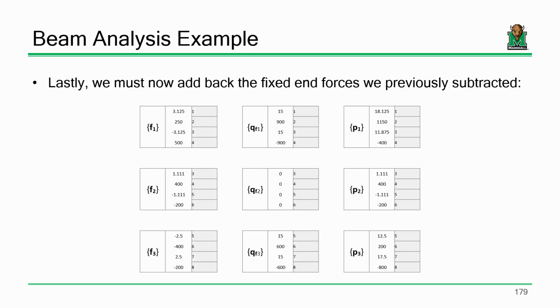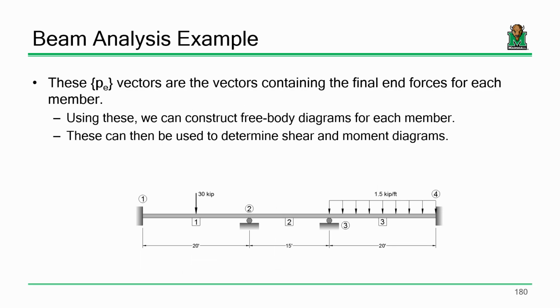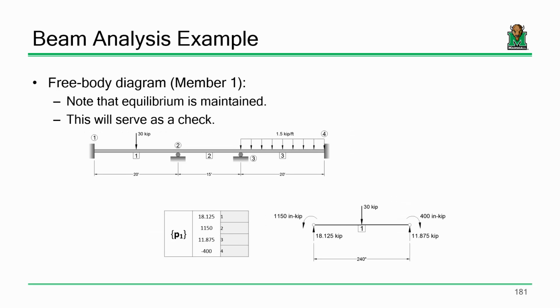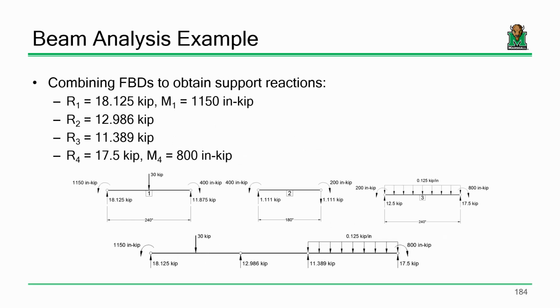And we took these final solution vectors, and we took each one of them and said, you can look at each one of these members and see that those forces achieve equilibrium for each one of these members. Just take any one of them, sum moments, let's say I sum moments here, and you will find that the sum of moments spinning in that direction equals the sum of moments spinning in that direction. So sum of moments equals 0. Same thing for this one, same thing for that one. Superimpose those results, and you can get your finalized support reactions for the whole structure.